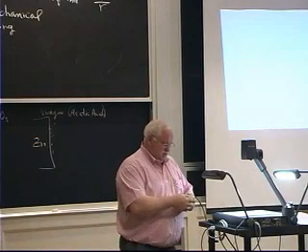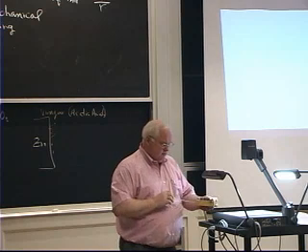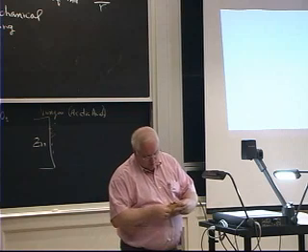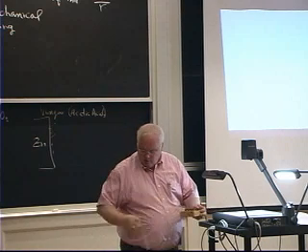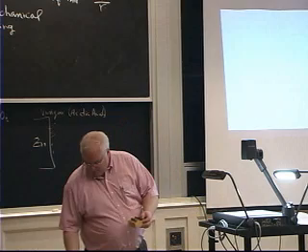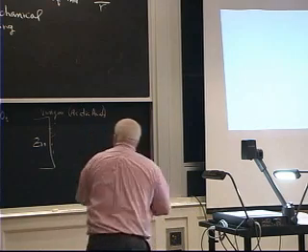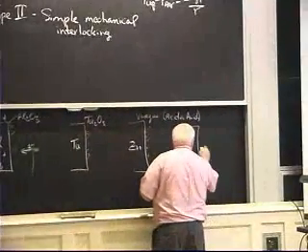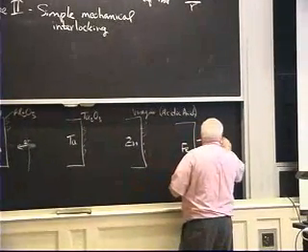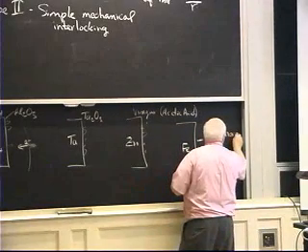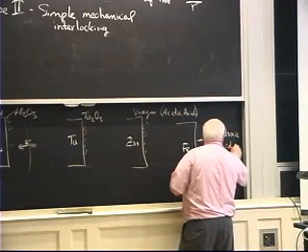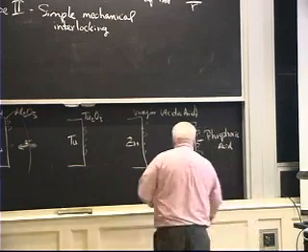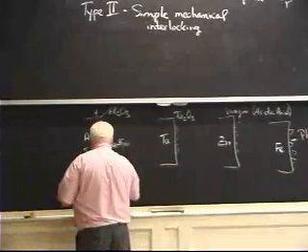Now another thing to talk about: porous surfaces. After World War II, we learned how to cold form steel. And the key to learning to cold form steel happens to have been learning to phosphate the iron surface. So if I have another surface here that's iron, and I put it in phosphoric acid, I'll get an iron phosphate on the surface, which is very rough. I can also take chromates, and I can do it on aluminum surfaces.